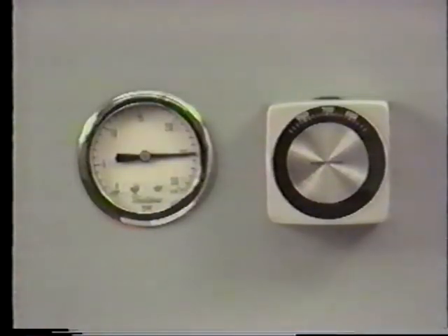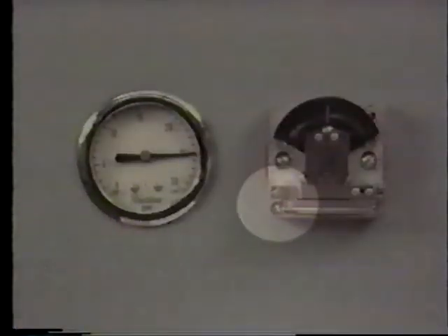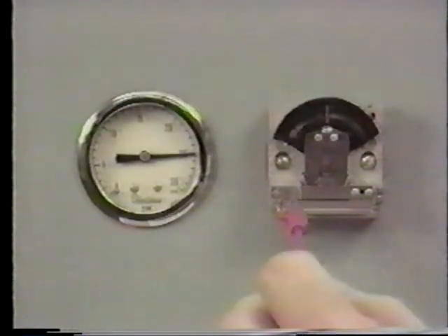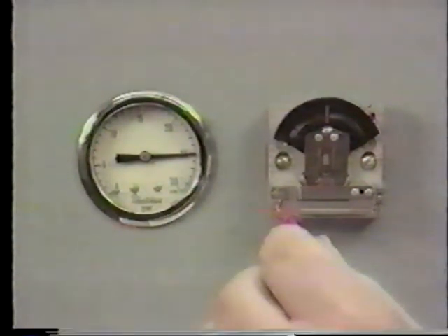When 21 to 25 psig is supplied to the main air line, the night bimetal controls the branch line output. The night set point adjustment is made here under the cover in the lower left corner of the thermostat. Using a calibration tool, turn the night set point scale until the night set point dial indicates the desired nighttime